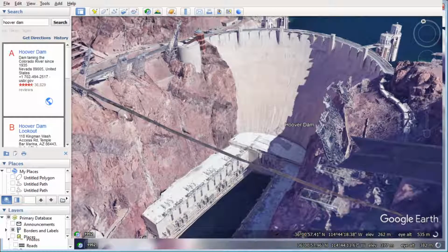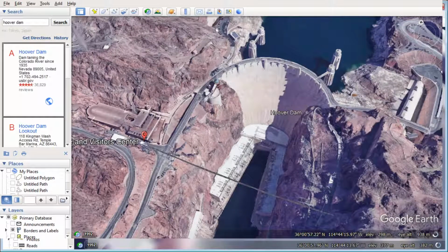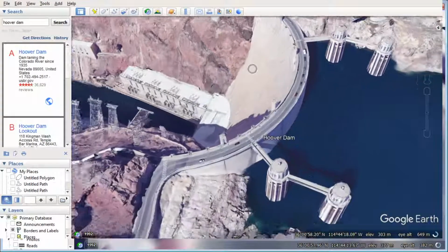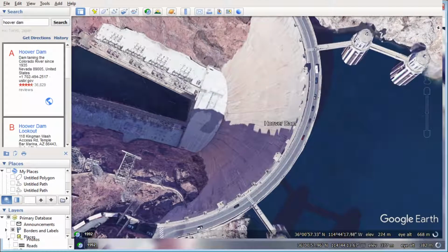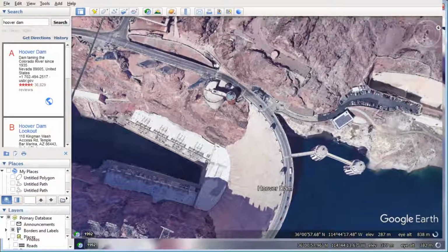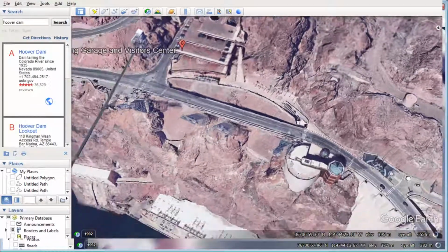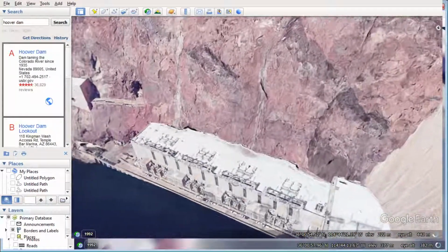In this case, the pipes are not running through the dam because that would compromise its structural integrity, since it's not a very massive dam. The cross section is quite thinner compared to the previous dam, and therefore the pipes are run through these mountains and released somewhere around here.